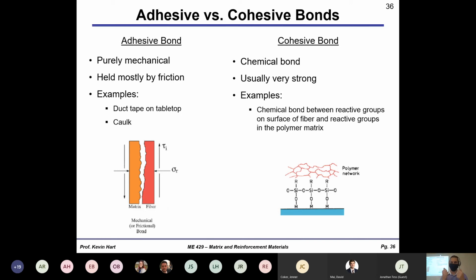All right. So these cohesive bonds are really what we're after. And it's part of the reason that we apply the sizing to the surface of the fibers. Remember that sizing is that aqueous spray that we put on the fibers that gives additional chemical functionality to the surface of the fiber. All right, so if you have a good sizing, that sizing will offer chemical cohesive compatibility with your surrounding matrix phase. And that's what we're trying to show in the bottom right-hand image here: you have the silicon dioxide surface, which might be like the surface of a glass, and you have a reactive R group, which is part of the sizing that can then actually react with the polymer network, this cross-linking epoxy network, which might exist. All right, so it gives you this additional strength and bond that is really nice to have and really offers the best load sharing possible when you're talking about getting, let's say, your composite into compression, where we know that fibers generally without this load sharing would be absolutely terrible.